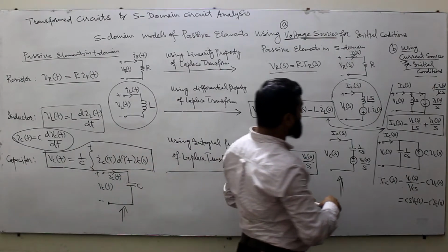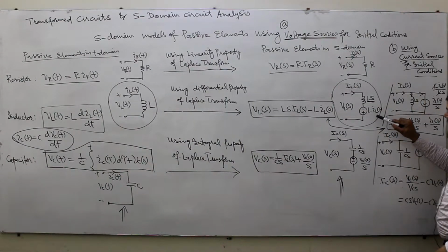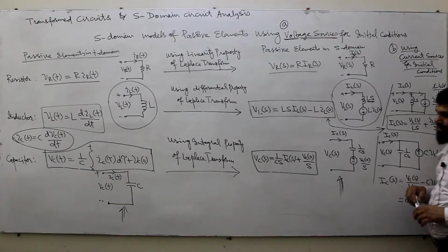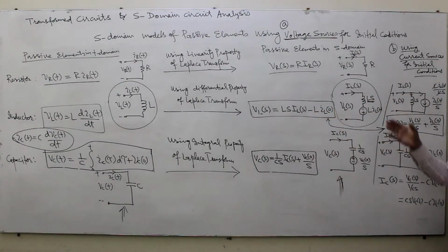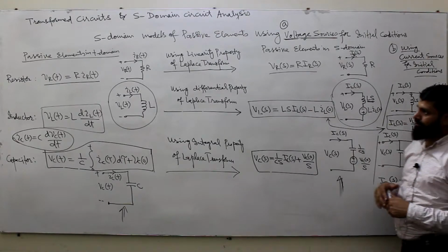They will be replaced by components that also depend on the zero initial condition, because when you are dealing with passive elements like an inductor or capacitor, they store some energy if they have been connected to a voltage source or a current source. Accordingly they save some energy, and those energies are part of the circuit to be shown if you want to do the proper analysis.